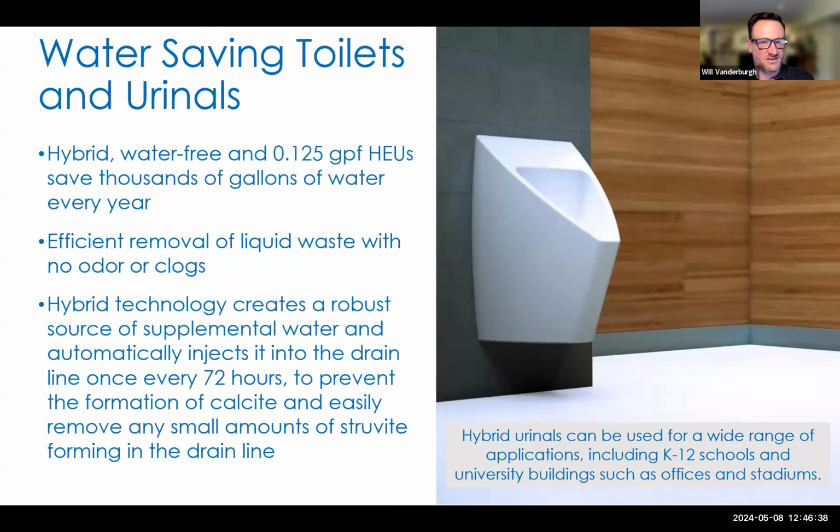It can certainly be used in school applications, but we find that they're not ideal, just from the challenges of the abuse that they would stand up to, more so than the traditional urinal type design. A water-free urinal uses some kind of a gel cartridge to stop the odor from coming back up into the washroom, as opposed to having a trap that a traditional urinal would have. And then some of them are also hybrid, so they use some kind of a water rinse on some kind of regular basis to prevent calcification in the drain pipes beyond the urinal.